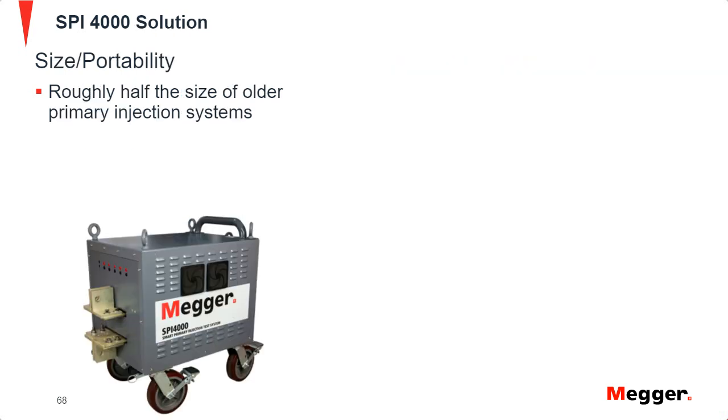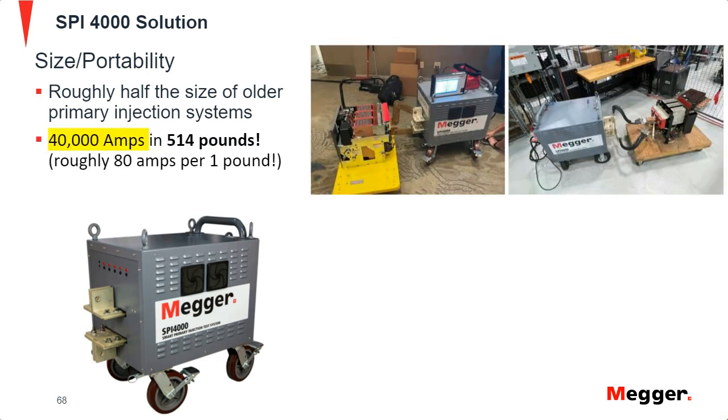So SPI 4000, the reason that it's such a hit right now, again, is the size of it. It's roughly half the size of the older legacy test sets that we were mentioning before. Seen here pictured on the top right, you'll just see smaller 1600 amp rated breakers right next to the SPI 4000. Its output through a breaker has been tested to be 40,000 amps. If you dead short it, it can be higher than that.